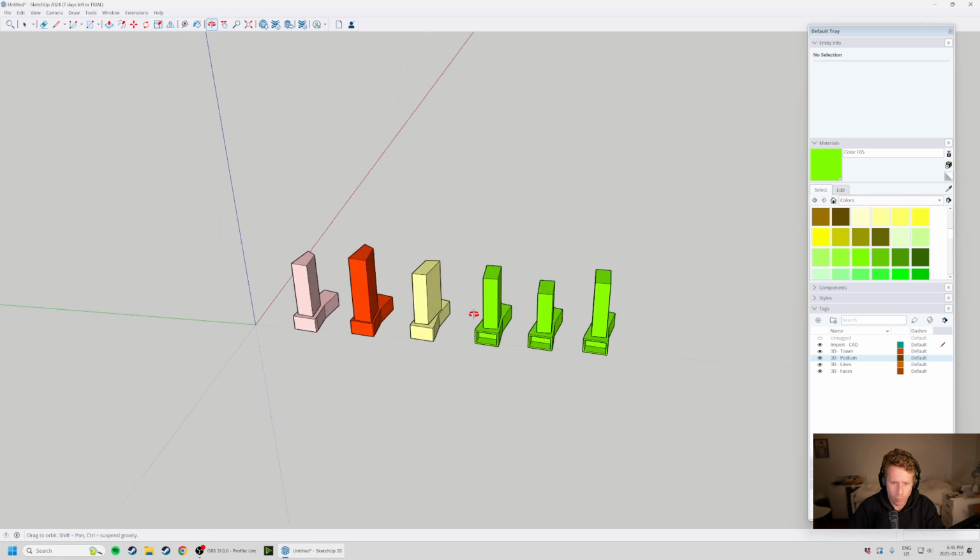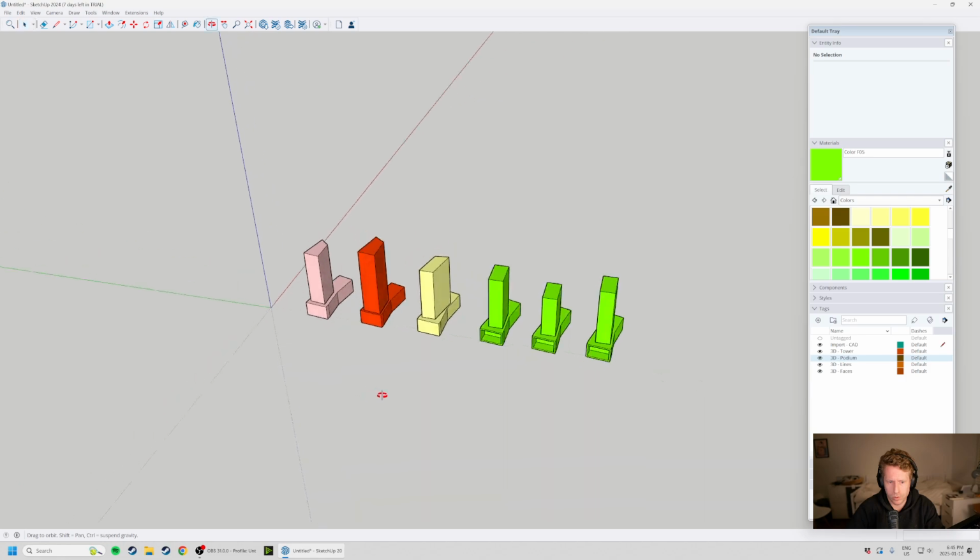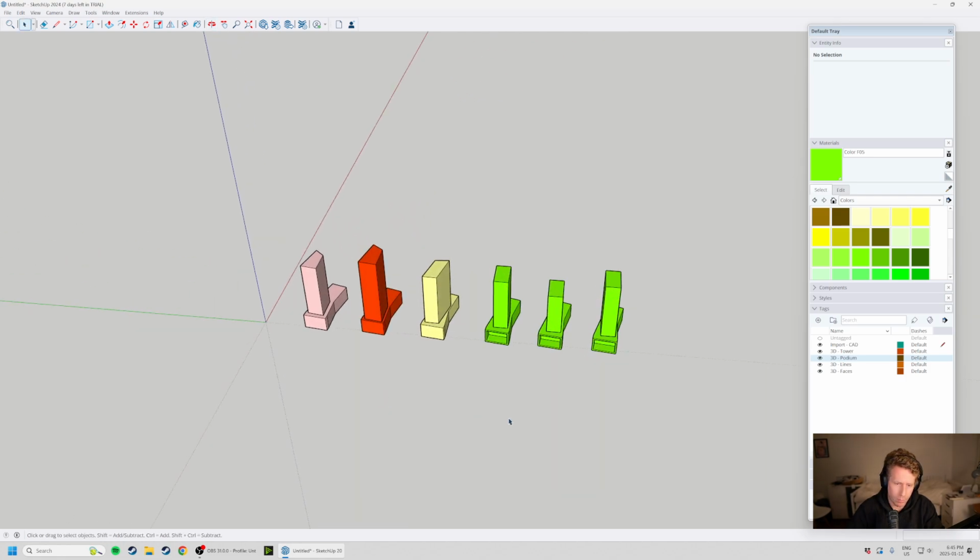For me, one really powerful thing to do, which I'll cover in a different video, is to import some CAD geometry and start to trace out what you want your building to look like. So most projects will have a survey at a minimum. Maybe they've got some existing plans somewhere. And you can use that. You can actually do File, Import.